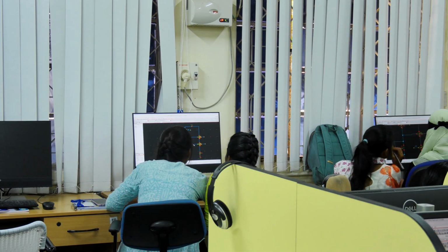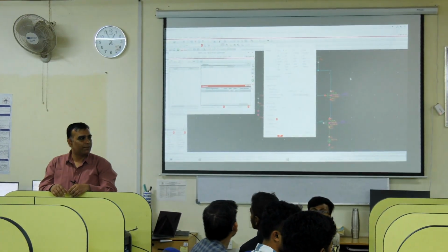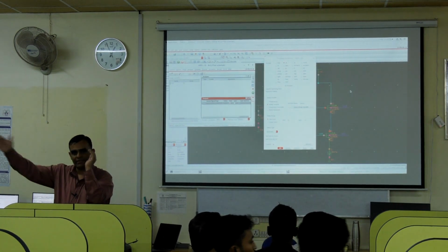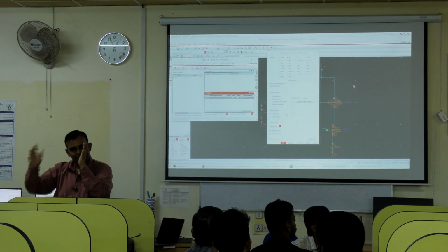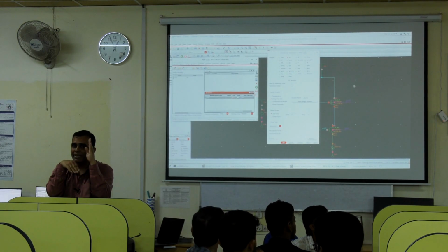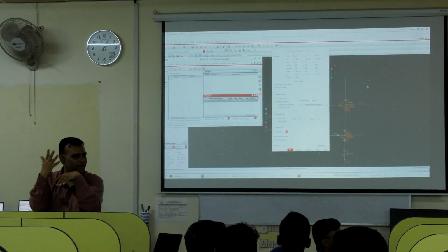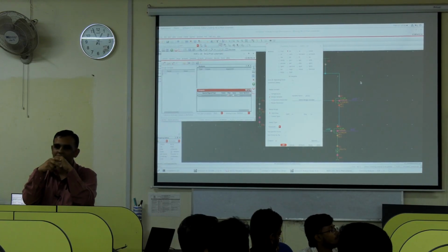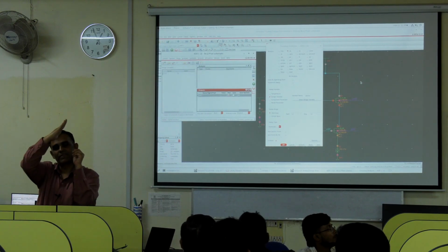Here is a question to all of you guys. If you have done it properly, what you would have got is on your x-axis the result, photocurrent, which should be in 10 to the power minus 12, minus 9, minus 8, minus 7, and so on and so forth. And that's in a decade scale, right? It's 10 times. On your y-axis, you have a linear scale. You have got 2.7, 1.8, and so on and so forth voltage. So what's the relationship between x and y? What kind of relationship do I expect to see? My x is logarithmic, y is linear, and my response is kind of a straight line.